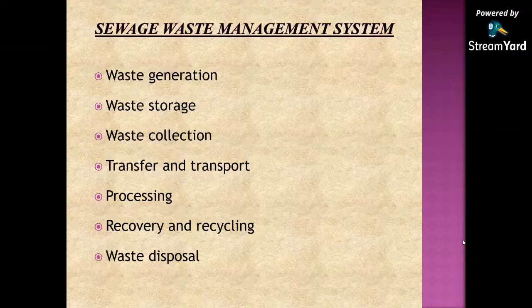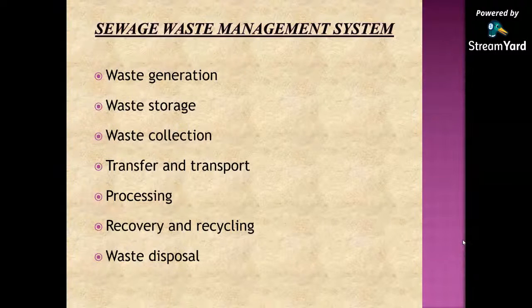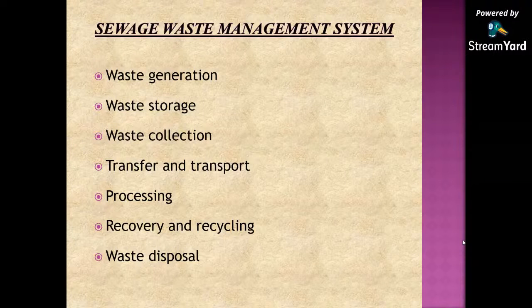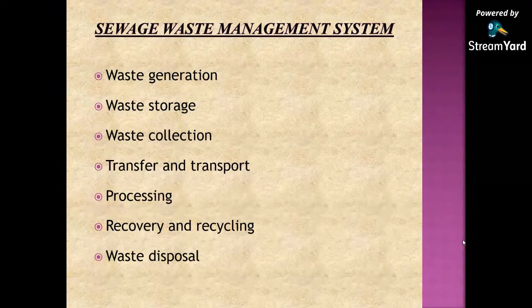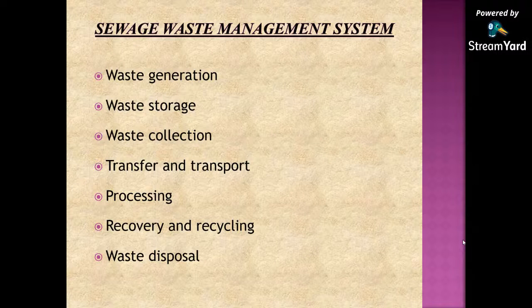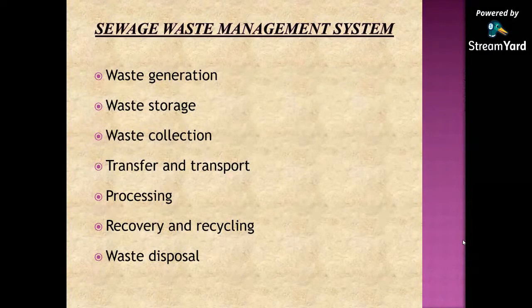A modern sanitary landfill is a method of disposing solid waste without creating a nuisance and hazard to public health. Generally, engineering principles are followed to confine the waste to the smallest possible area. They reduce it to the lowest particle volume by compaction at the site and cover it after each day's operation to reduce exposure to vermin.